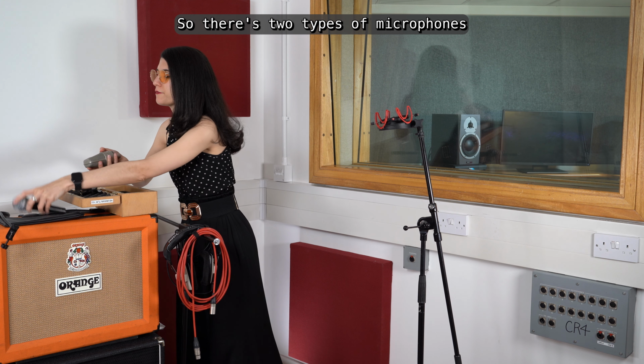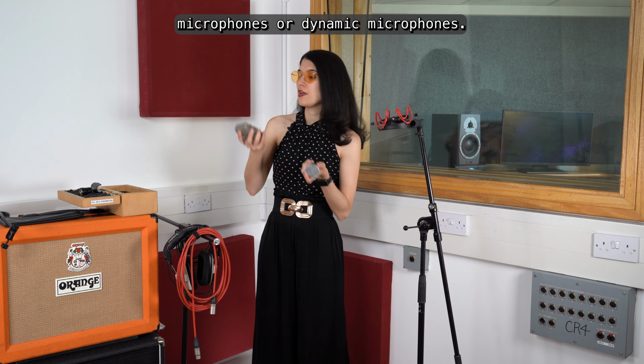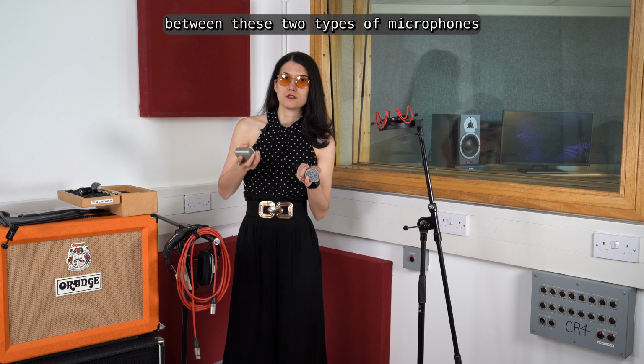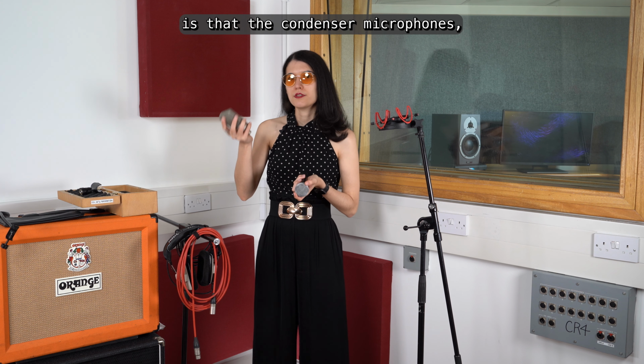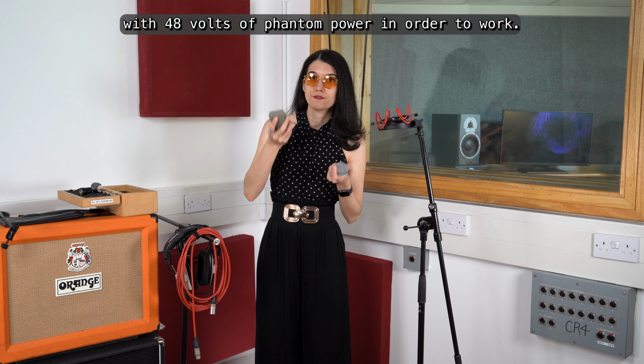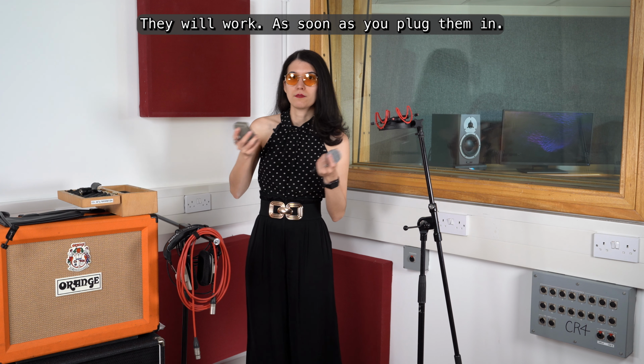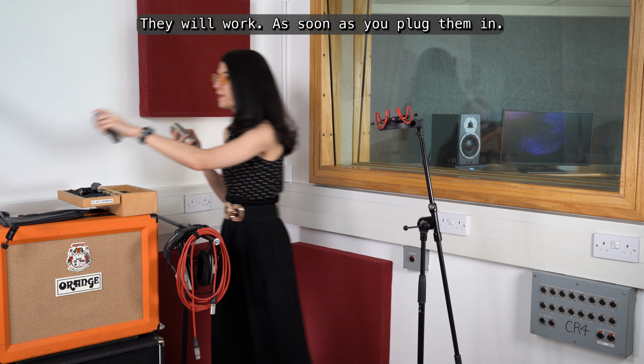Then you can position your microphone. There are two types of microphones that you might be using in this room. You're either going to be using condenser microphones or dynamic microphones. The main difference between these two types is that condenser microphones need to be charged with 48 volts of phantom power in order to work, and dynamic microphones don't. They will work as soon as you plug them in.